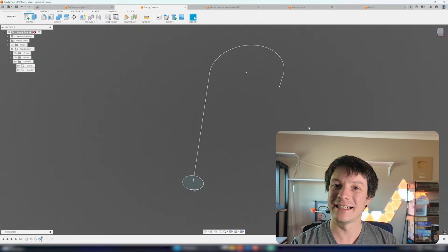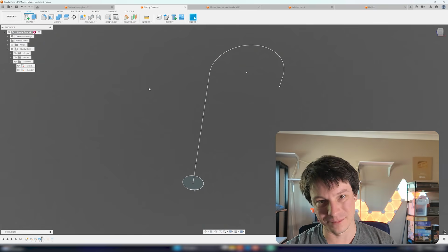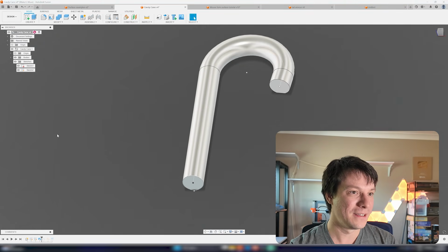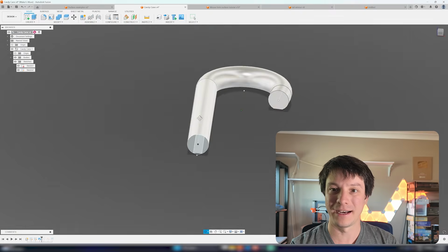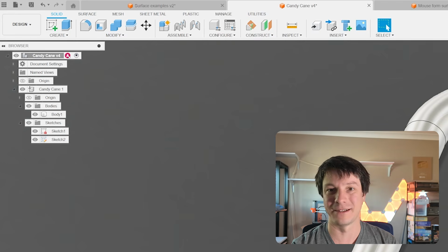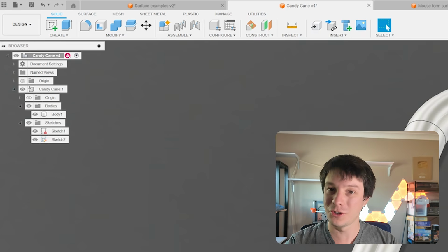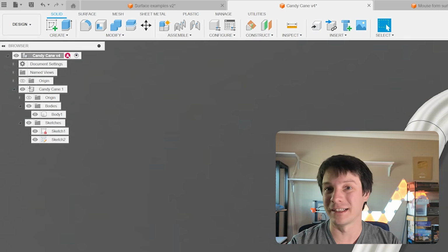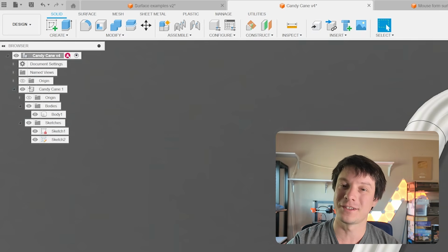And then the path is a simple candy cane style shape. So the sweep then takes that profile and path and creates this solid body. And you can see here in the drop down, we've got one solid body there. Now to turn this solid body into two separate bodies that can be printed in two different colors, I used a surface sweep. But there's one little thing you can do within sweeps that's really powerful that I took advantage of, and that's twisting along the path.